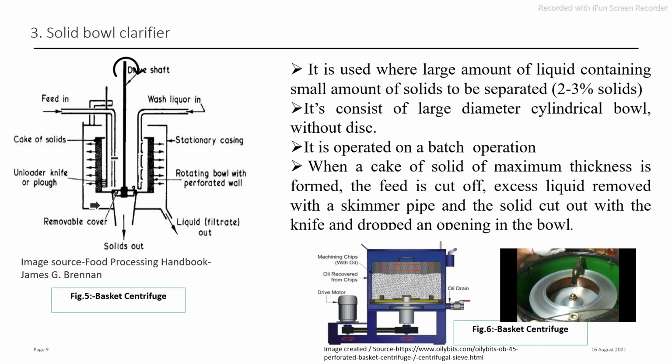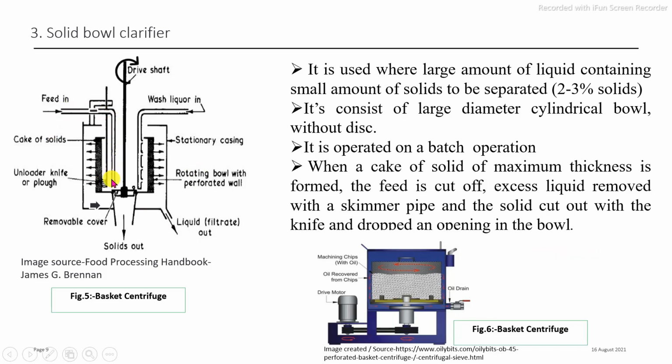In the working, the feed liquid enters at the center of that rotating bowl, and after that, due to the centrifugal force, whatever the liquid constituents are, they pass through the filter media into the outer casing, and they are discharged at the bottom. In the feed containing suspended particles, these suspended particles are deposited on the filter media and form a cake.